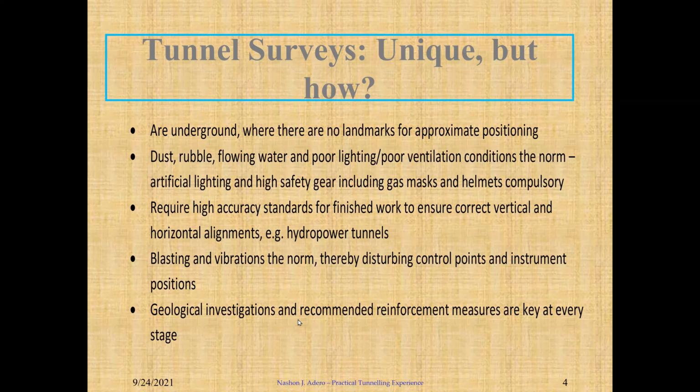So geologists would conduct their tests, and based on that, inform the team where we needed steel reinforcement underground and where we needed shotcrete instead of steel, and where we didn't need any intervention because of the strength of the rocks in that section. Maybe you have granite. In other areas, you have very loose rocks that would need reinforcement with shotcrete, and others with steel plates. And those are key parts of safety underground.